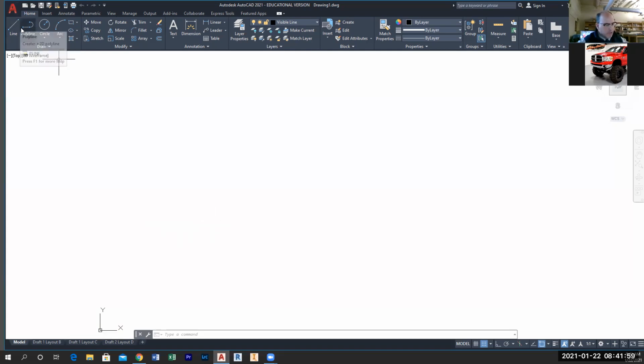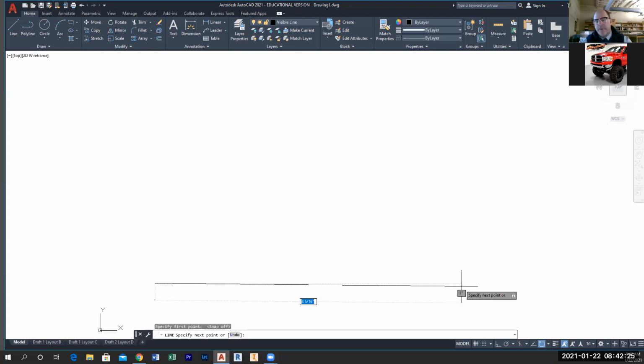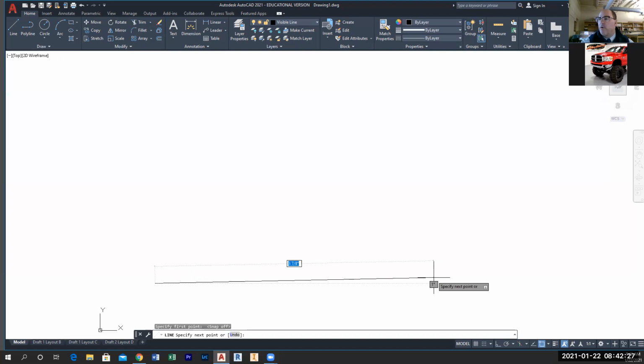If I'm looking at this drawing, I talked to you guys when we did sketching about width, depth, and height. Those are the 3 major dimensions. So I'm just going to go ahead and draw a line. You notice my cursor is jumping around a little bit. That's F9, my snap to grid. I want to take that off and make it a little smoother, okay? So all I'm going to do is draw a line. And this is going to be an ortho line. I hit F8, ortho line.